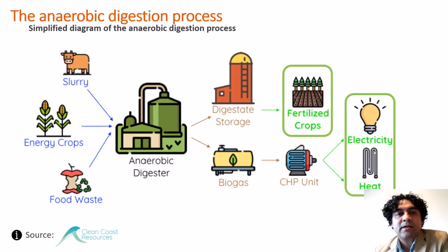facility. The anaerobic digestion process results in three products: biogas, typically between 50 to 70% methane. After impurities have been filtered, the biogas can be burned in a cogeneration of heat and power unit to generate electricity. Second product, digestate, a high-quality soil fertilizer rich in nitrogen, phosphate, and potassium. Third, heat generated from the combustion of the methane gas that can be captured and put to use as either steam or hot water.